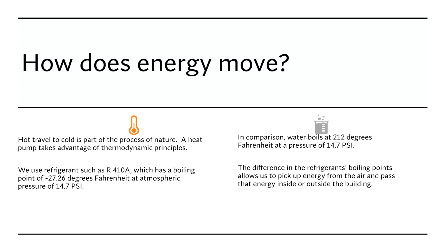The ability for refrigerants to absorb energy from an environment, even though it would be seemingly cold to us, is relatively warm to it. So, as we stated here, our R410A will boil off at 27 degrees below zero Fahrenheit. But if we're operating at 20 degrees Fahrenheit, we literally have a 47-degree temperature difference between the state of the refrigerant being a vapor and a liquid.